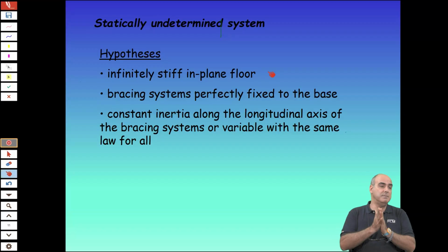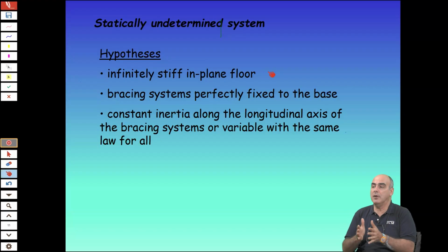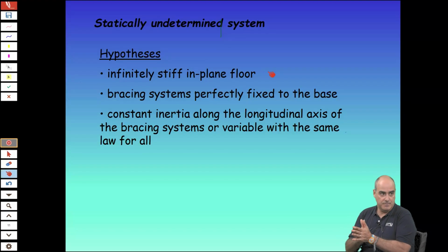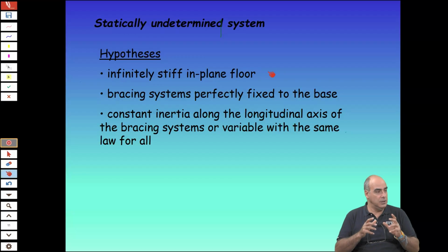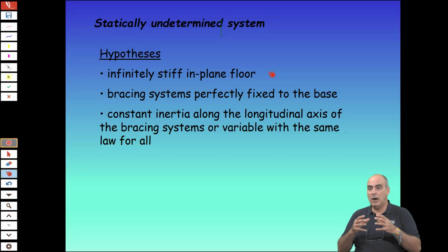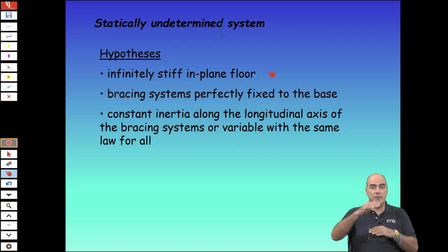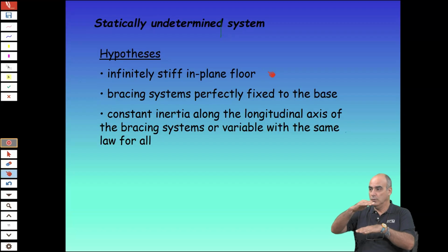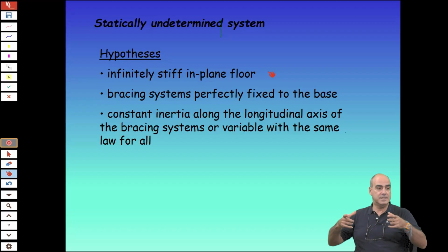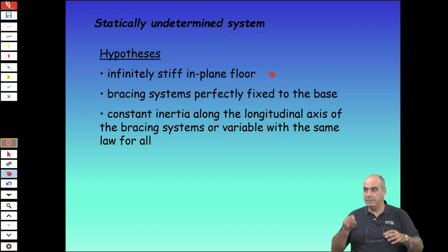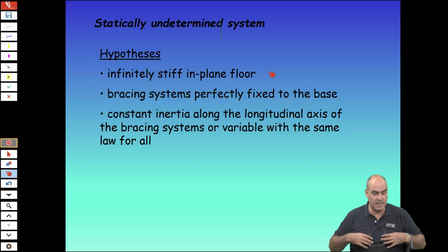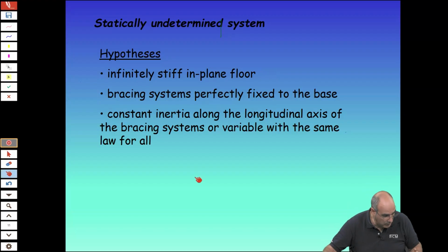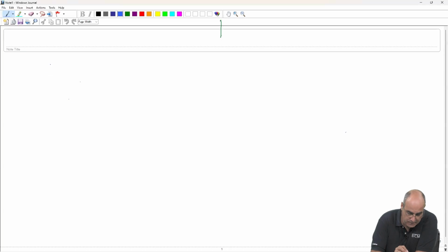So what does this mean? This means that you have always the same ratios between the inertias. And you can adopt a simplified method that even for a multi-story building, you can just limit yourself to one story and consider the slab with its elements and the force which pertains to that story.